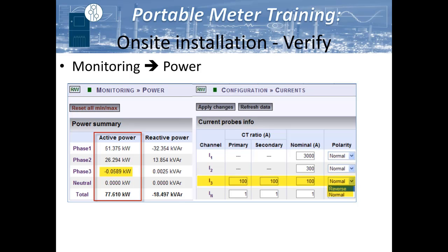In this case, they had to go in and fix it to change the CT ratios to make sure that it came out and made sense. So this is one of those instances where you want to make sure that everything is correct. So, always go over when you do a hookup. Even if you don't have a computer, everybody's got a phone with them. Make sure you've got that app on there and you log in and all the information makes sense. Okay, next slide, please.